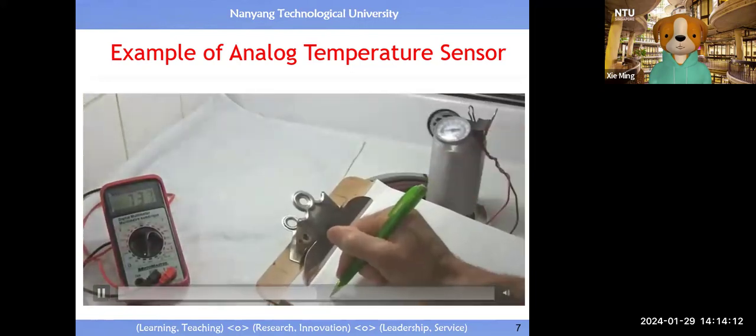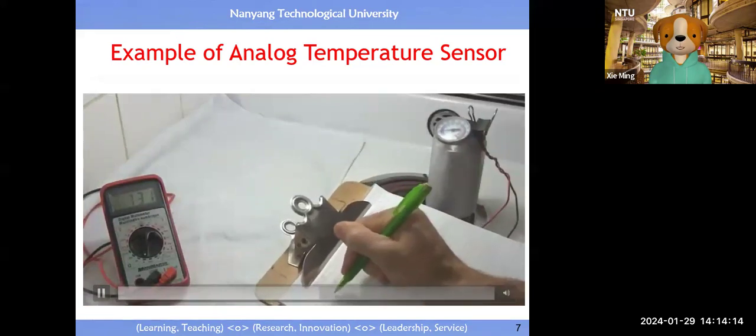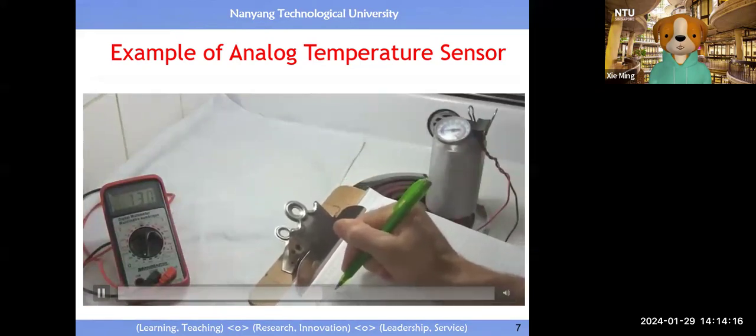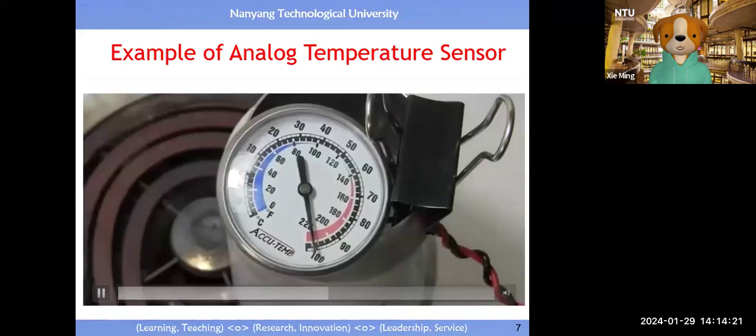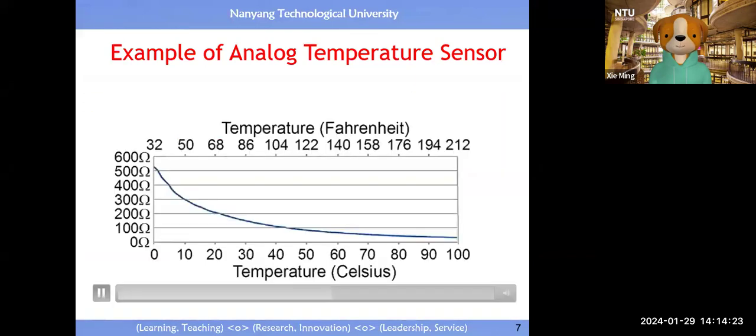I then started recording the resistance on the meter and the corresponding temperature on the thermometer as the stove element heated up the water. I stopped once it reached boiling, which is 100 Celsius, or 212 Fahrenheit. And here's the chart drawn using the data from my table. As you can see, the resistance decreases as the temperature increases. You can also see that it's a curve.